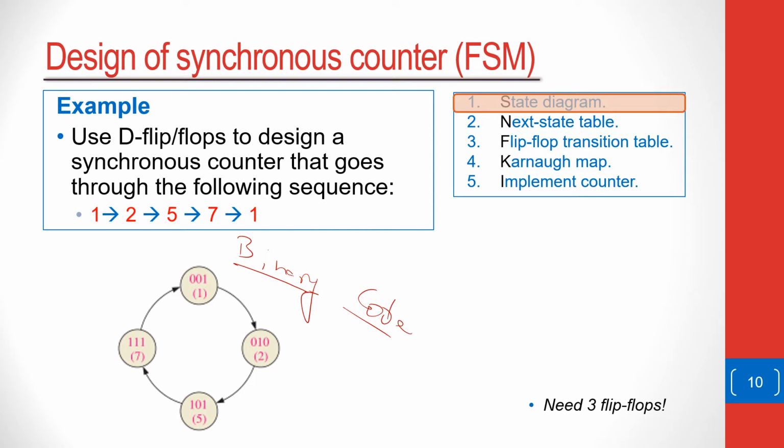For these 4 states, or 4 digits, that we need to have here, in binary we need a maximum of 3 bits to represent them. Because we have a maximum of 3 bits, we can tell that whatever we do, we are going to need 3 flip-flops in our design. So this is what the state diagram first tells us. We encode our states into binary code, sketch clearly what transitions it needs to go through, and write them in binary code. Afterwards, you will know the number of flip-flops or memory elements that you need.